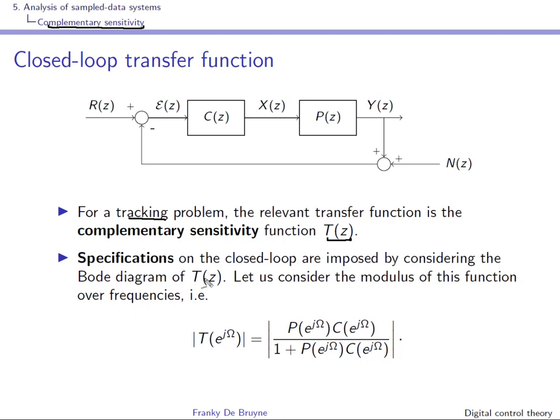So what we'll do is apply specifications on the closed loop, and we'll impose these specifications on the Bode diagram of T, and we'll consider the modulus of this complementary sensitivity function as a function of the frequencies.